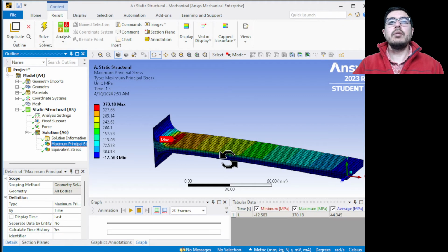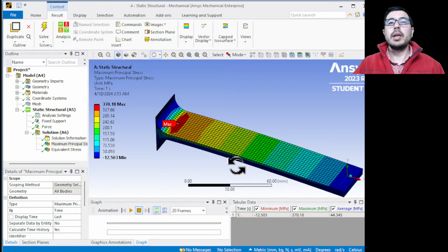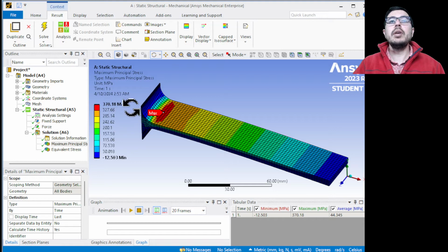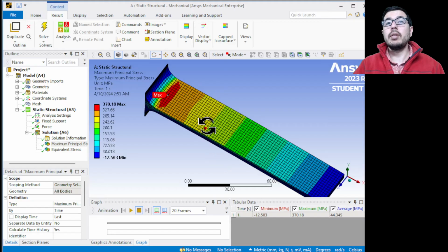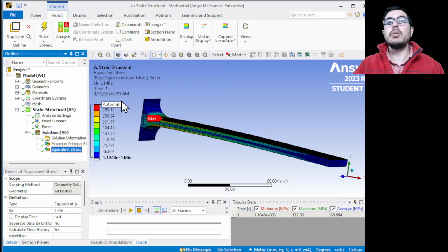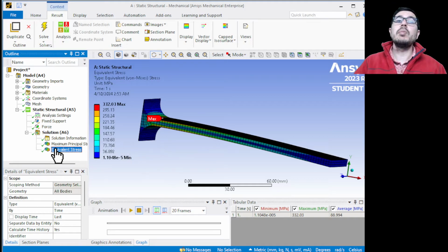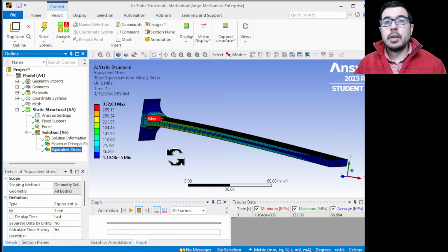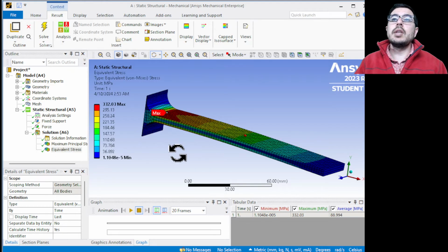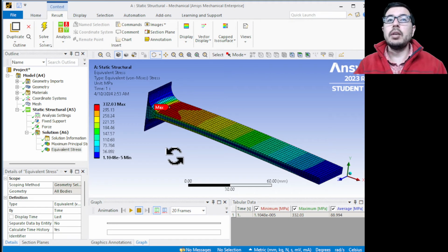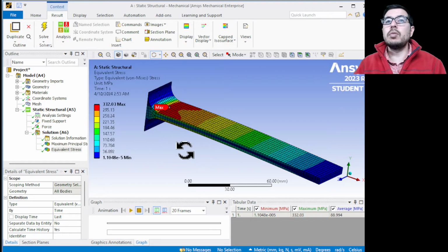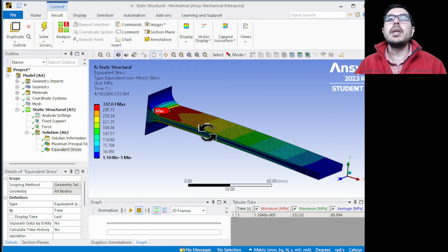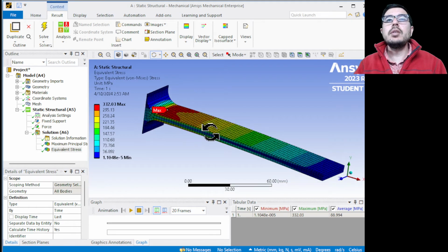All right, so now what is our maximum principal stress? 370 megapascals, right? And we predicted 360 megapascals, and it's about in the right location. The equivalent von Mises stress is 332, so it's actually a little bit less. Remember, von Mises is looking at the maximum distortion energy, so it's essentially the equivalent stress to uniaxial loading using maximum distortion energy, and it's kind of a rough estimate, which is close to Tresca, which is half of the shear stress. So this is good enough for us to continue.